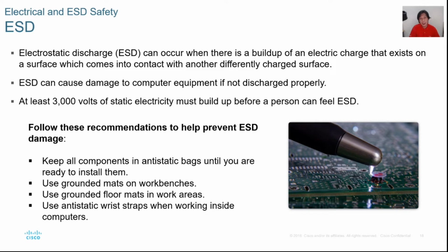Remove the AC power adapter from the outlet before you conduct assembly or disassembly. Those are the safety precautions first that we need to adopt in terms of ESD and the electrical voltages.